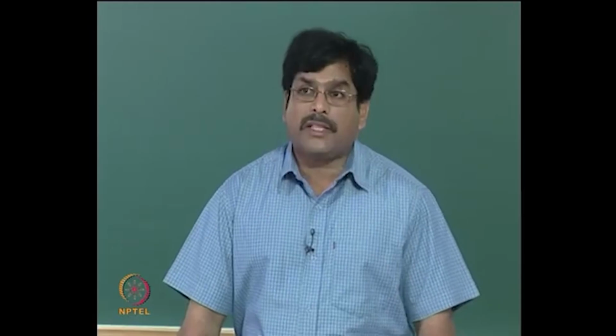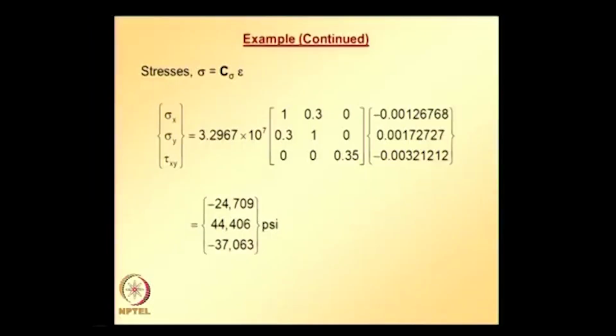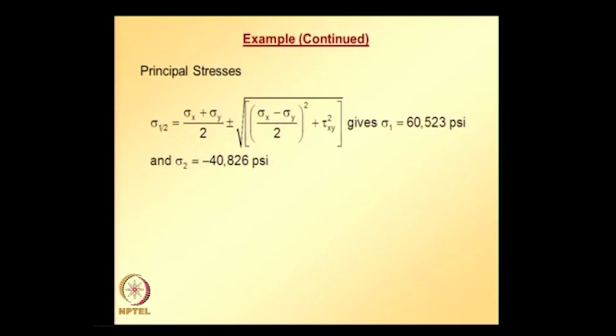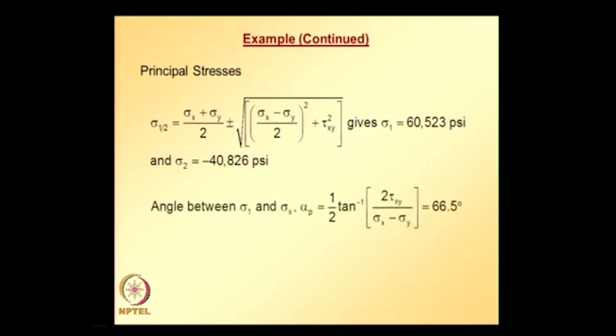And once we got stresses we can calculate using these quantities principal stresses for subsequent usage and failure criteria and all other details required, angle between sigma 1 and x, sigma x and effective stress, and these calculations can even be repeated for element 2.